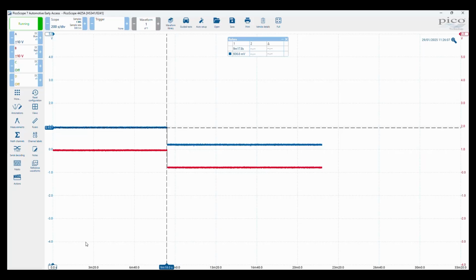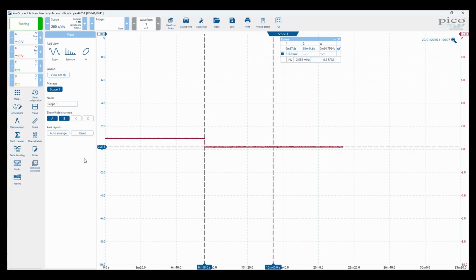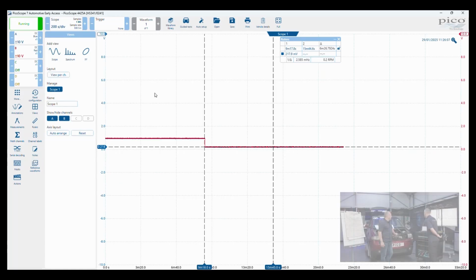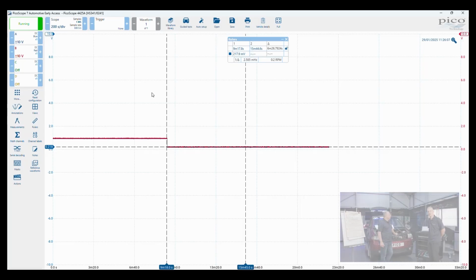We seem to have been at this level now. Let's pull this ruler down. We are now at 217 millivolts. I'm going to use the reset feature. If we go to the views and reset, we can see that both waveforms are sitting on top of one another, which means there's no differential, and no differential means no current flow. Wouldn't it be great if we could wait all day long? Maybe as we carry on through these tests we'll see that drop to 0.